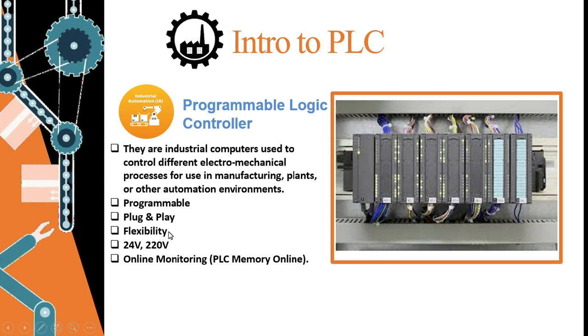What does flexibility mean? If I want to use a microcontroller for a car wash system, I cannot use the same microcontroller for a car parking system. Why? Because with a microcontroller, I have to design a PCB sheet. But in the case of a PLC, we don't need to do that. We just download the program of the car parking system into it, and then I can use it for car parking. If I download the program of the car wash system, then I can use it for car washing.